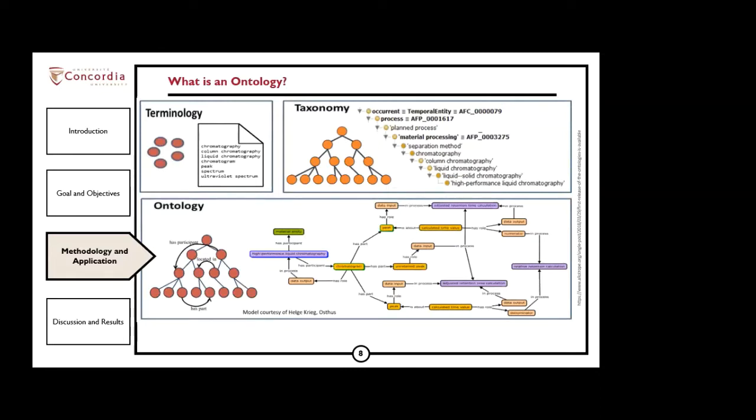Once I put it on a hierarchy, creating a dictionary of it, let's say what types belong to what type of systems, then I'm forming a taxonomy. Now, how these HVAC systems, the parts, the building parts are associated together, what type of relationships are being formed between those is the ontology relations. Basically, ontology enables me to capture a concept, in my case, HVAC, and show me what concepts are included, how these concepts are related together, and what type of restrictions between these axioms exist.